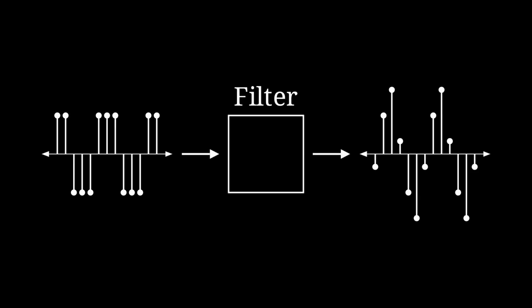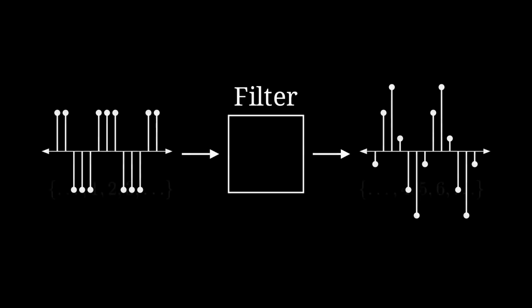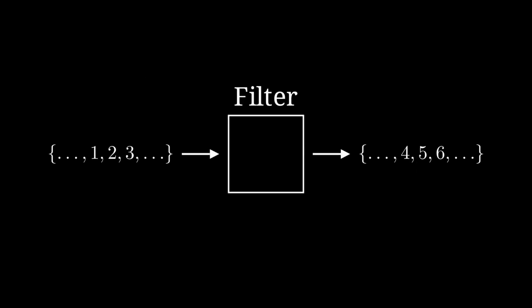So what is a FIR filter? Well, first, let's talk about what a filter is. In the context of DSP, a filter is a process that converts an input digital signal into an output digital signal. Mathematically, you can model these signals as infinite sequences of numbers, and you can then model a filter as an operation that converts arbitrary input sequences to output sequences. We often denote the input sequence by x[n] and the output sequence by y[n]. There are many classes of digital filters with different key properties. We are, however, only concerned with causal FIR filters because that is what the SNES's hardware implements.